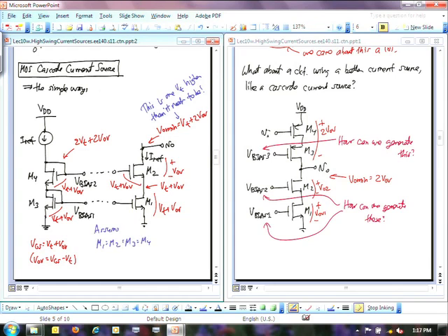You'll see that they generally are, but even if they weren't, then I would have to put in VT2, VOV2. But VTs are about the same amount, VOVs are about the same amount. Now, VTs are usually 0.7 volts, and if there's body effect, there'll be a difference. We have to worry about that, but I'm just doing a simplified analysis. We're all the same, and in general, you'll see that they usually are.